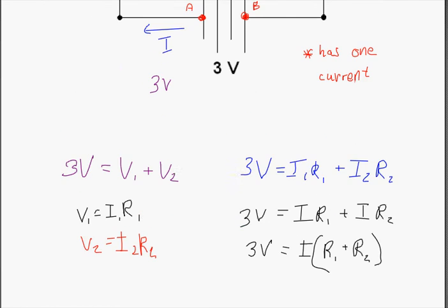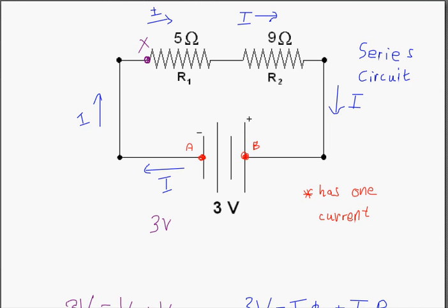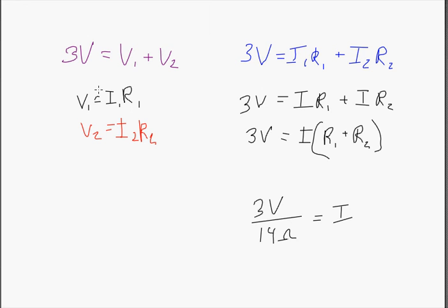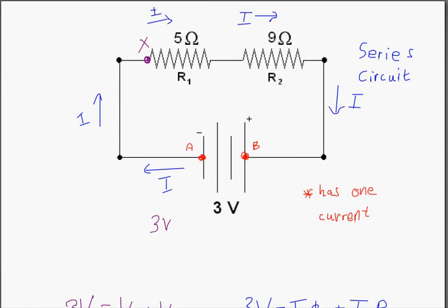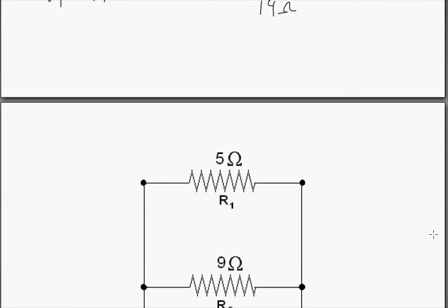Now, then you'll know, okay, well, let's go back and talk about this. And we can say, well, we said this, guys. We have this before. These are important now. We can say the voltage lost to resistor 1 equals the current, which is 3/14 amps, multiplied by the value of resistor 1, which is going to be R1 is 5.